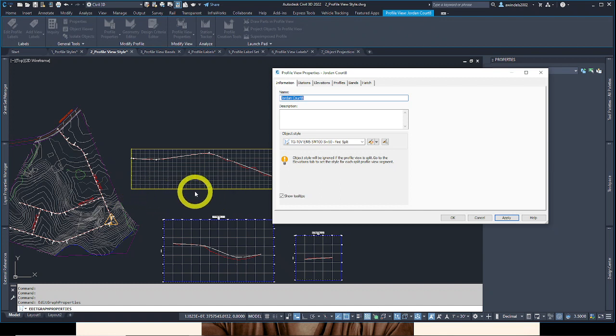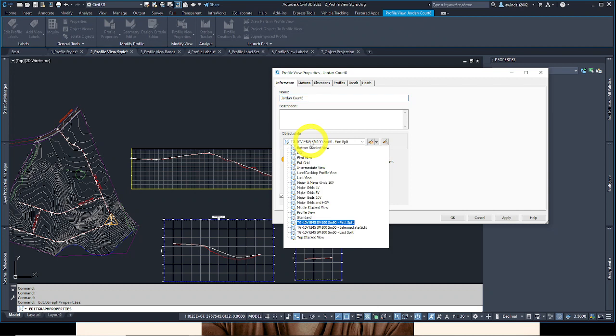The x-axis normally stays 1 to 1, usually stays true, 1 foot equals 1 foot, okay? But the z-axis, a lot of times on profile views, most times, is the one that gets exaggerated. So they can be stretched. If it was 1 to 1 vertical exaggeration, 1 vertical equals 1 horizontal, then there would be no exaggeration. But a lot of these are stretched.